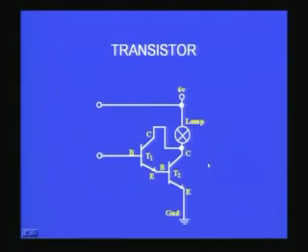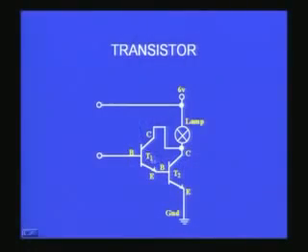And then there is another aspect which I wanted to talk to you about. If I have a gain of beta for one transistor, then if I use a combination of transistors, 2 transistors for example, then you might be able to enhance the amplification factor still further. Here what we do is a well known configuration which is called the Darlington configuration, after the name of the person who designed this.